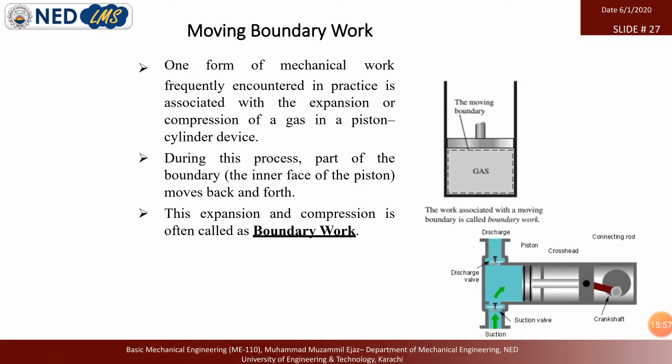In our daily life we have a common application of a compressor. When you go to any tire shop, you can see this kind of compressor which inflates your tire with air. So it is a compression process. In this figure you can see that the air is coming from here, then it is held. When the piston moves here, it compresses, and then the valve opens, and air is released that way. So it is a compression process.